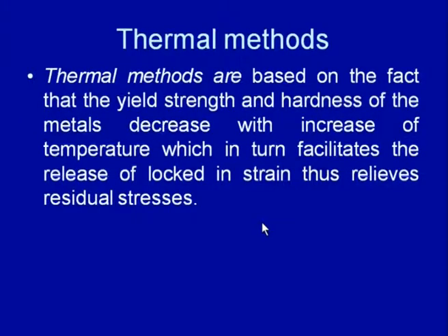Now, we will see the thermal methods which are used for controlling the residual stresses. Thermal methods are based on the fact that the yield strength of the material and the hardness of the metal decrease with the increase in temperature. When the exposure is given to the weld joint at high temperature, the reduction in the yield strength and the hardness of the metal facilitates the release of the locked-in strain and thus relieves the residual stresses.